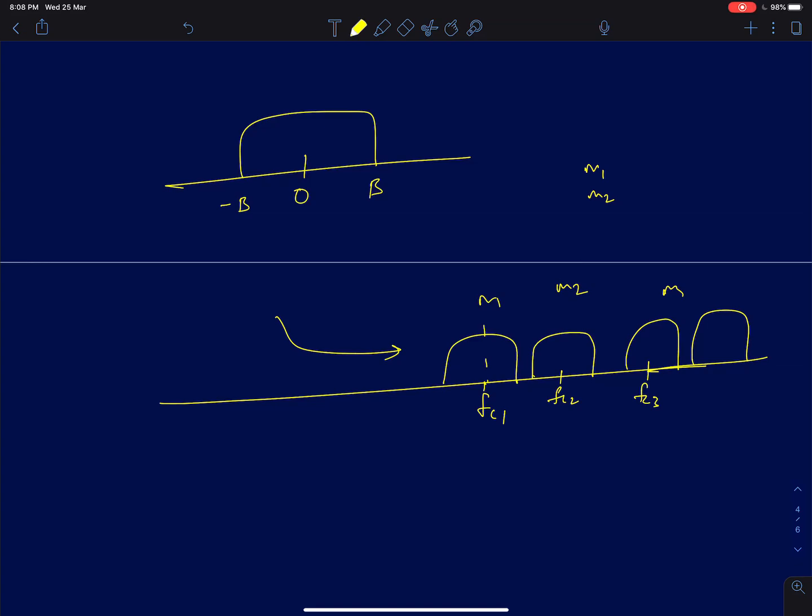Here we are assuming we don't know the message signals. If you know the message signal a priori, then you can cancel it out. But if you know the message signal, there is no purpose of communication in the first place. Since you don't know that, you can't distinguish them. So in a wireless system, to distinguish them, each user is given a frequency slot. Each user now transmits at a different frequency.